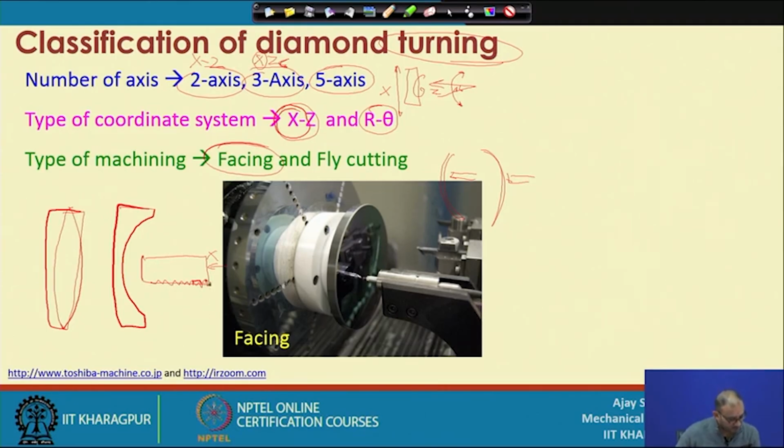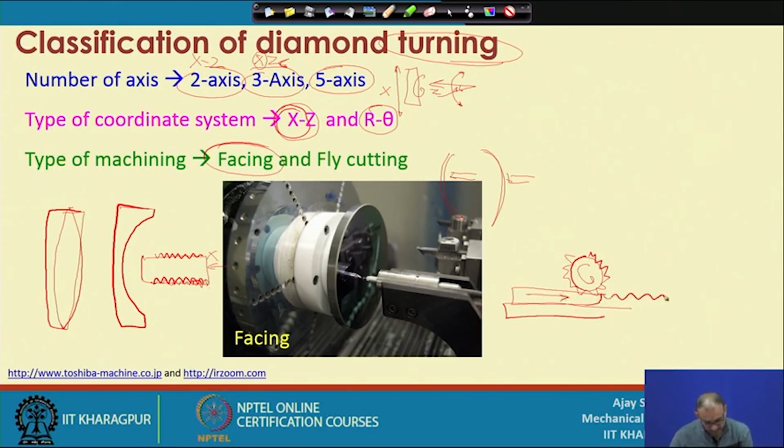Suppose here you have some type of features created, something like this, on all the surfaces, and you take this particular wheel here. This is that wheel, and these are the features we have created on the surface, and there is a polymer sheet which is coming in this. So, you rotate this particular part and then you move this polymer sheet through it. We get all these features transferred onto the polymer sheet, and there are different applications for a polymer material with a textured surface.